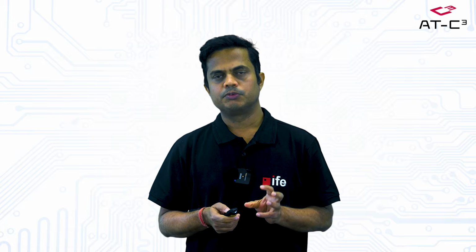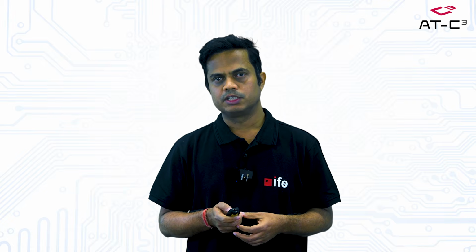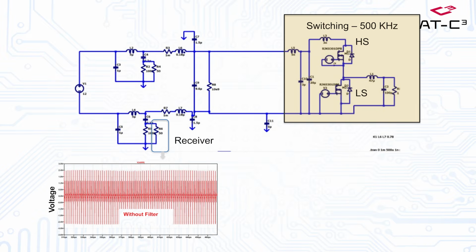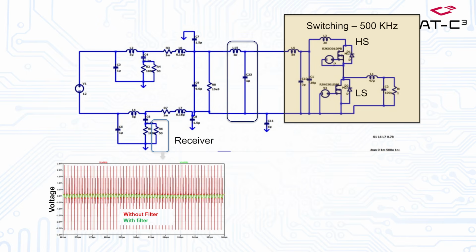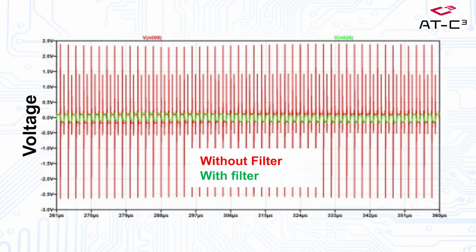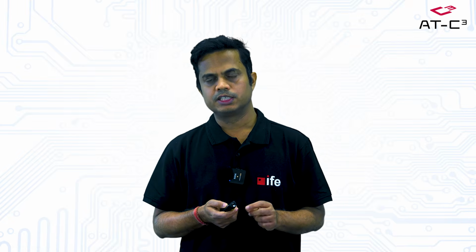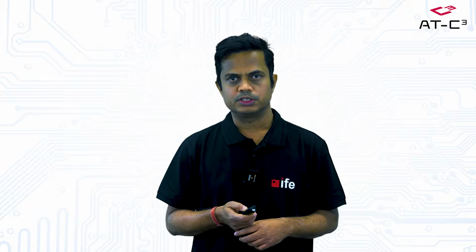Now let's check the impact of the filter on the emission of the buck converter. This is the buck converter circuit which we have seen before. This is the switching noise which is going out of the device. Now once I have put in the filter, we can see our noise has come down, as shown in the green line. It has come down drastically. So this shows that we need to optimize the filter, we need to find the correct values, and we need to find the topology.